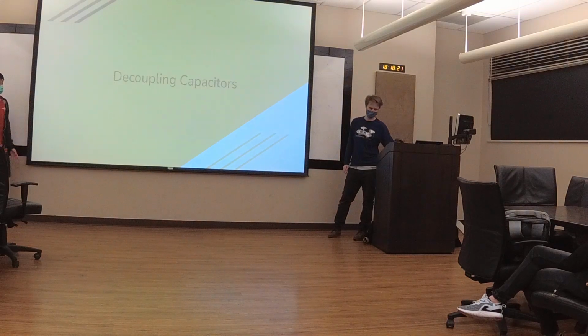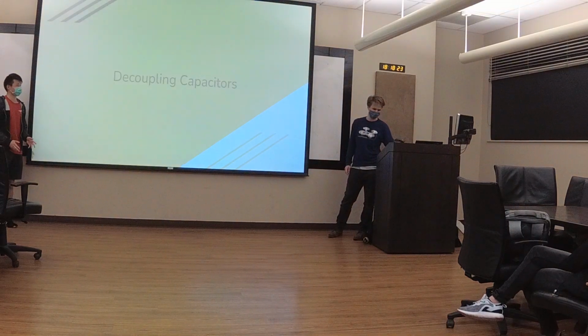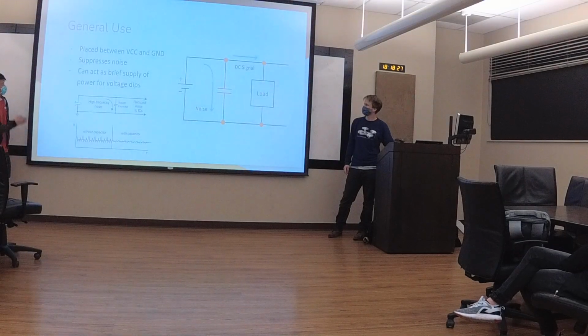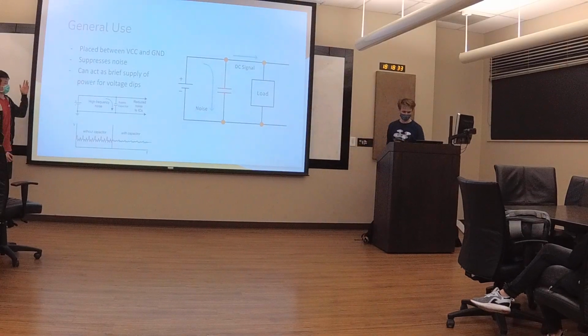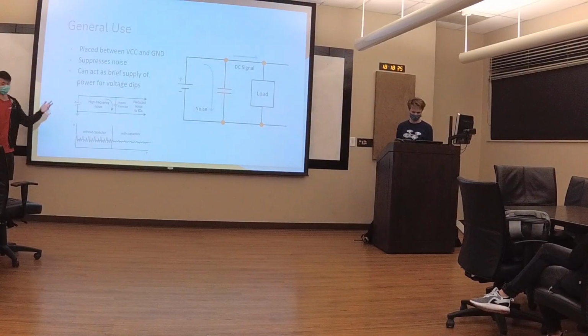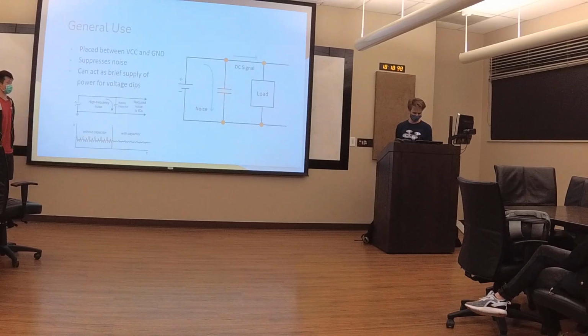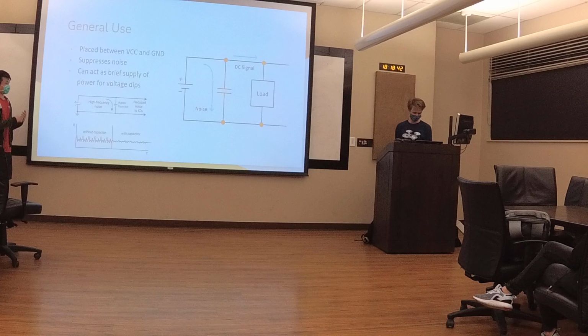Okay, so we're going to start on the actual topics that we want to talk about today. There's not that many, so we'll try to get through them fast. Decoupling caps. If you've worked with capacitors in the past, you know that they're commonly used for decoupling, a word that basically means they're helping us reduce noise. Every voltage source has some kind of noise; the signals aren't pure. They have some kind of oscillation around the ideal level, but with the capacitor, it will reduce that variation.